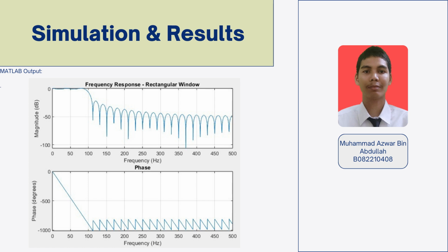And the third one is the frequency response. A magnitude response with a passband frequency below 100 Hz and a stopband frequency above 100 Hz. The passband shows good preservation of the 50 Hz sine wave. The attenuation in the stopband reduces noise contribution above 100 Hz, though the ripple effect could slightly impact performance. Overall, the FIR filter successfully attenuates high-frequency noise and enhances the 50 Hz sine wave. The filter's linear phase nature ensures no phase distortion, preserving the waveform shape.